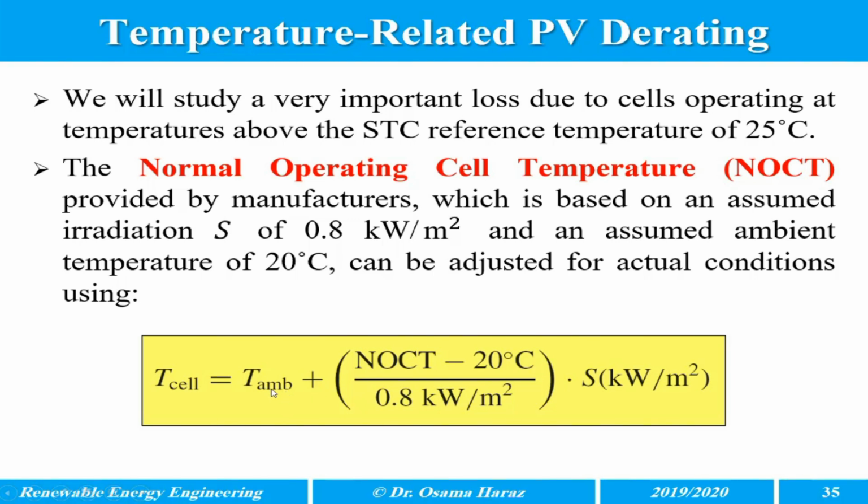So if I give you the ambient temperature and NOCT at the irradiation, you can find the temperature of the cell.